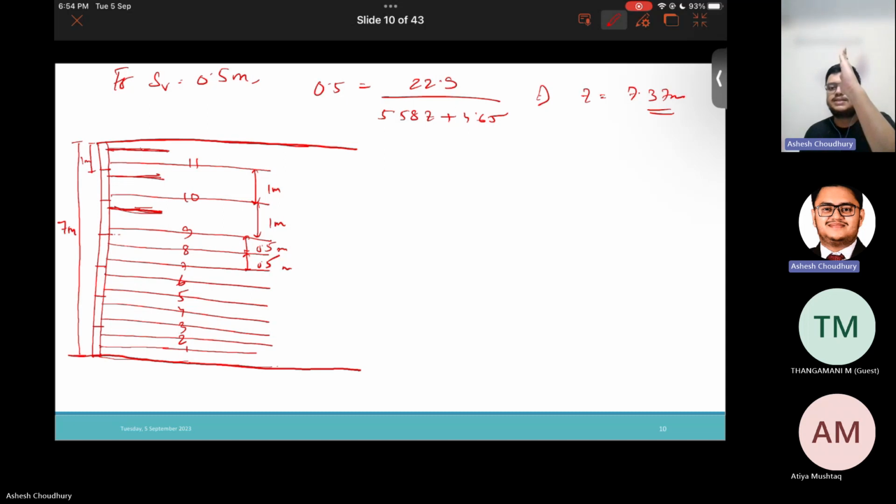Else what will happen? See, we have the facing block here. We are providing the reinforcement, right? So you can understand, due to this eccentric loading, one reinforcement you are attaching here, we'll get some eccentric loading, and the facing block might get displaced.